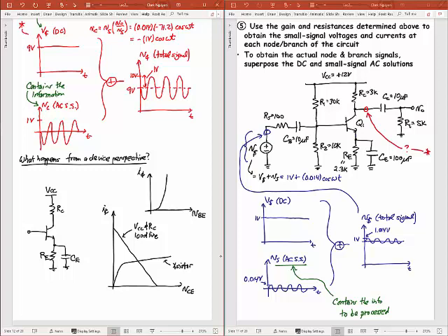And so what exactly did we do when we're making this amplifier work? There's my transistor there, and these are IV characteristics for the transistor. This is IC versus VCE. That's the characteristic right there. What I'm basically doing, and we've done this before, is taking the transfer characteristic from my active device, the transistor, and putting it together with the load line made by my load device, which for the real amplifier was RC in parallel with the RL, but to simplify things, I'm just saying it's RC right now.